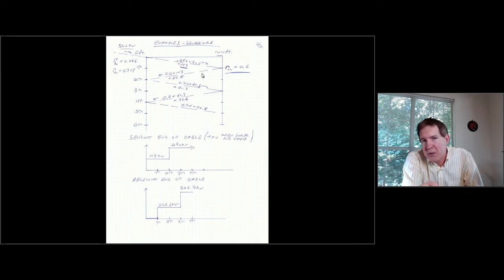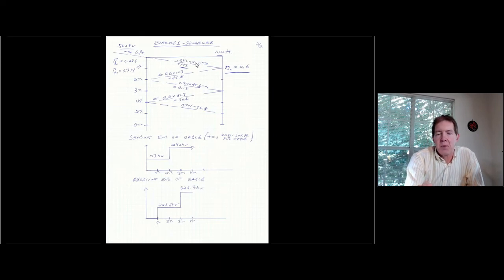When I do these pulse bounce diagrams, I usually show how I get the number, the reflection or refraction coefficient times the incident waveform magnitude. Then I also show the result. That way, if I'm debugging, I know where that 143 came from. So I got 143 kV.